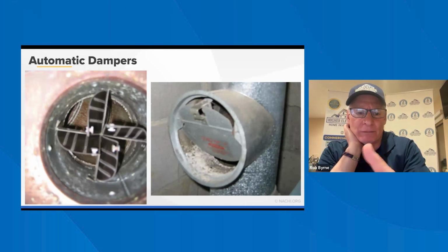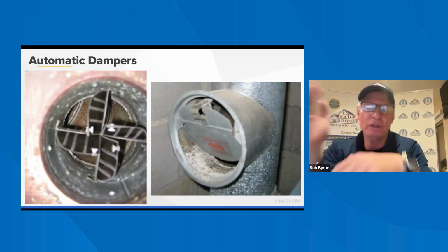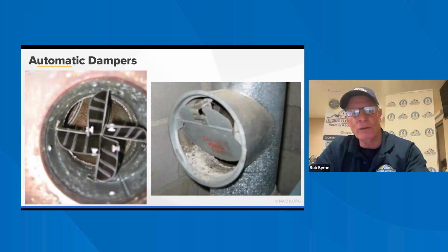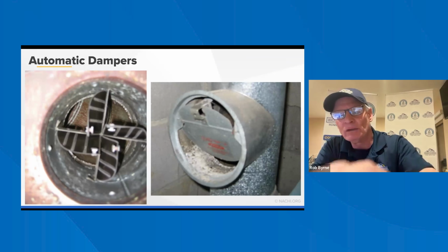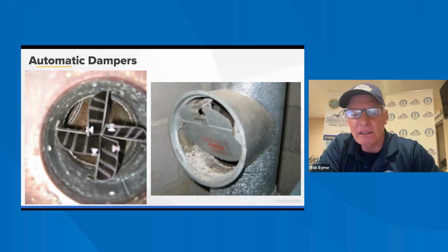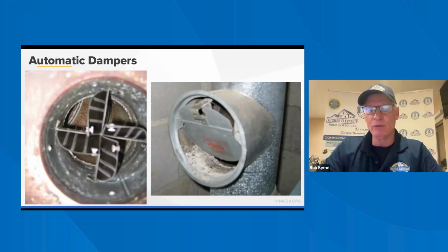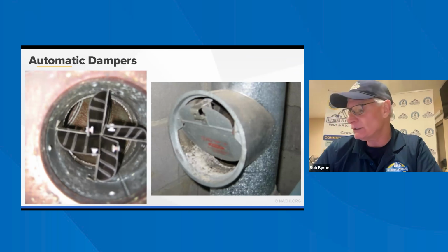And when the heating system starts up, the vent is not hot enough, so this kind of regulates it. So your main purpose on these things is to make sure they're functioning properly. You'll always see this one on the flue right above the appliance. Just want to make sure it moves freely and does its job.